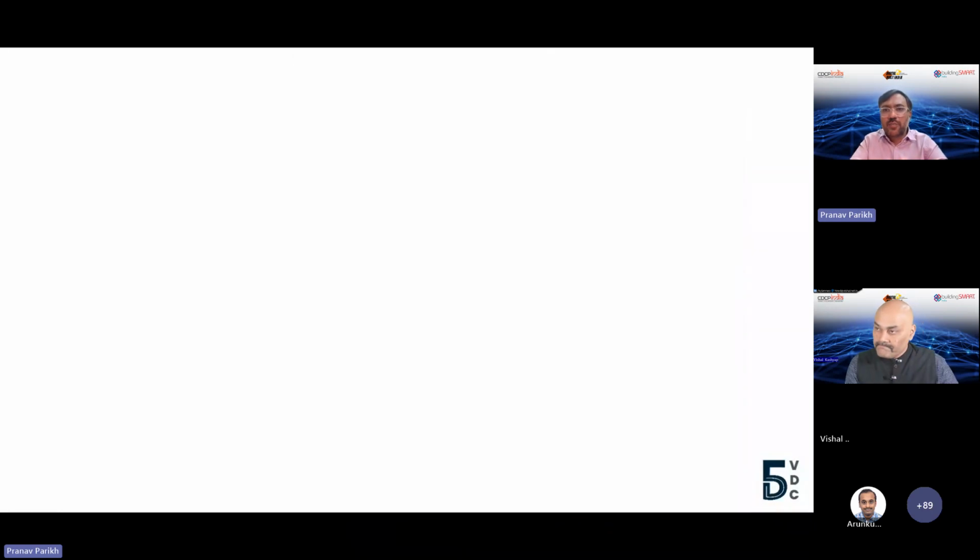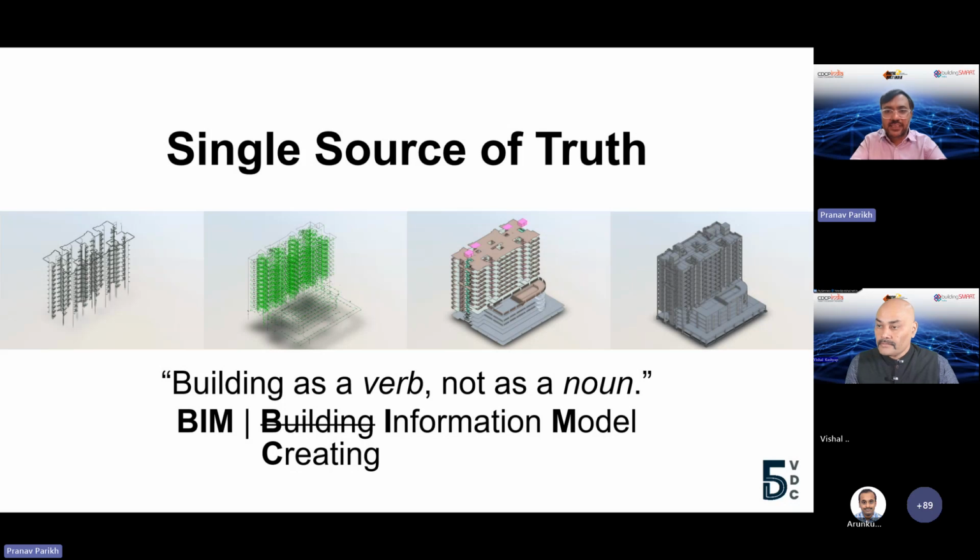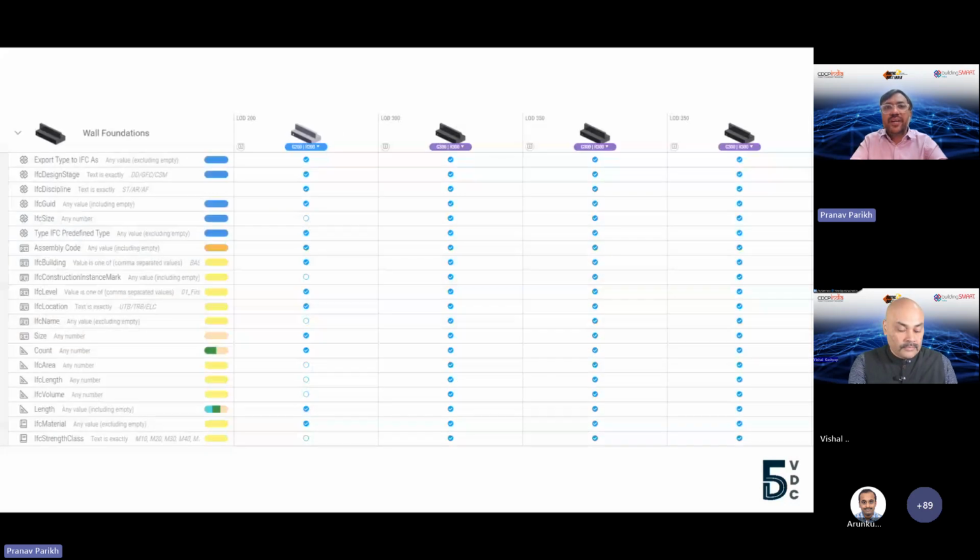every information is also added on top of the model. So furthermore, with the same, speaking the same language, single source of truth, the model element table focuses on each LOD requirement, LOIN requirement, which parameters need to be there, which parameter needs to have what kind of information. Unless this is standard, your BEP technically is incomplete and we will not be talking the same language.